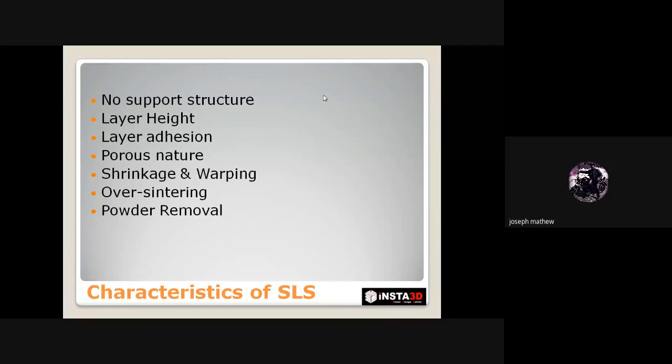Taking advantage of the whole build volume is very important when printing in SLS, especially for small batch productions. A bin of a given height will take the same time to print independent of the number of parts it contains. So regardless of the number of parts placed in the 3D printing software, the whole build plate should be covered with products in order to attain a good optimized printing estimate. Using the SLS 3D printing technique, you can go for low volume productions. That is, parts which require very low volume and which are mass customized can be printed on an SLS 3D printer.